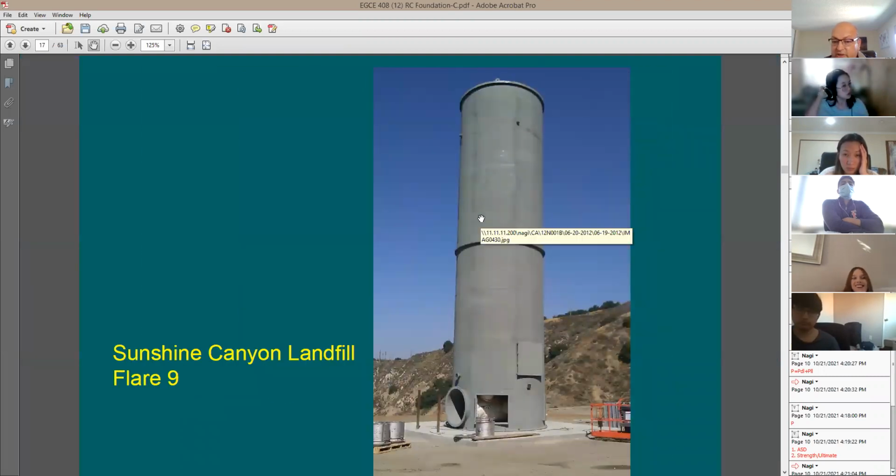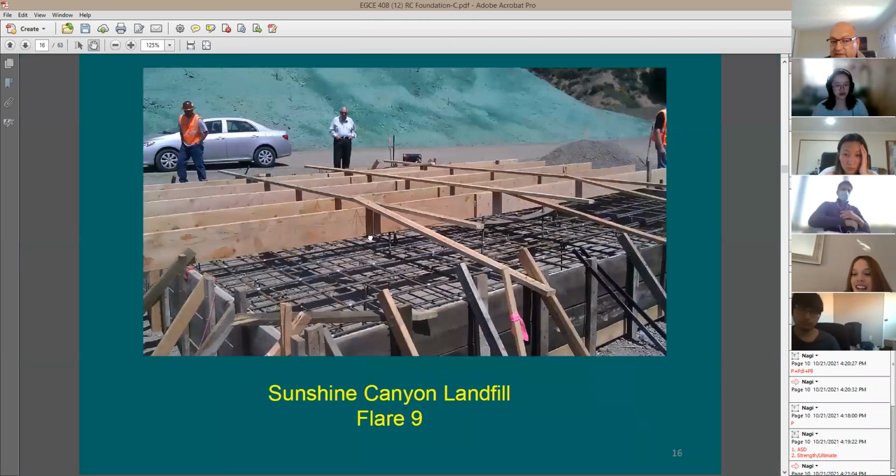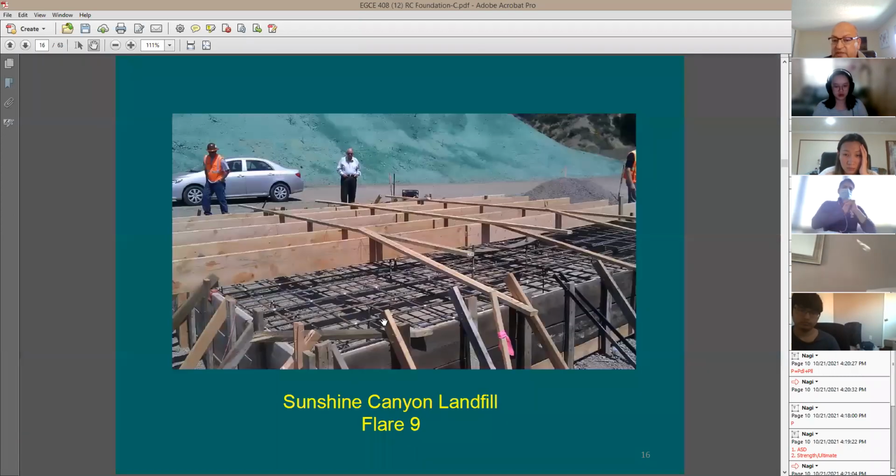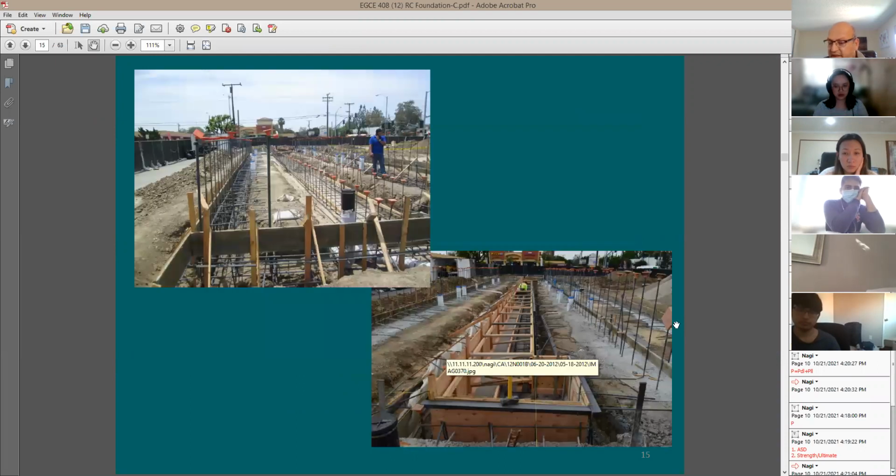So during the construction, we have this picture that was taken, and here's the pad size. It has top and bottom reinforcing, and because it was extended both ways, the excavation, they decided that they're gonna do formwork for the footing itself. So when they cast the concrete and they strip the form, the concrete footing was very clean from the sides. It's gonna be unlike this type of construction. It's gonna be like this when they strip the formwork.